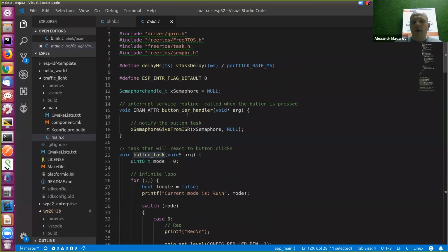And here we are using a special type of data, which is called a binary semaphore. Basically, it receives the data that we take in the main task and decides whether we need to flash the yellow light and then turn on the red light, or continue with the green light. That is the main principle of how the semaphore works.